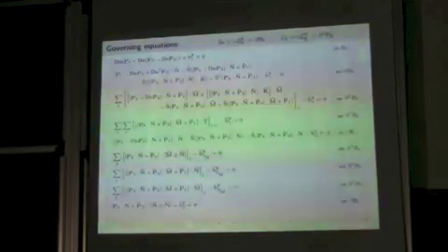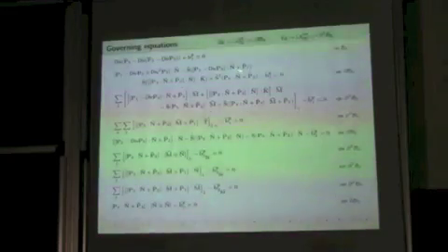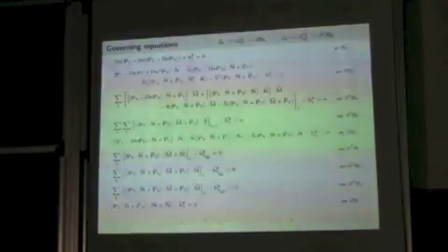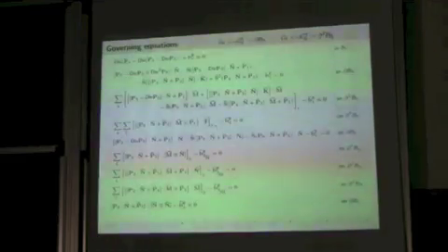It's difficult to see what's going on in detail, but for instance, it's interesting to see that your P hat 1, which is your surface stress, is adding to P2, which is the second gradient bulk stress, and to the divergence of P3, which is the third gradient bulk stress. So if you look at this structure, it tells you a lot, and we have also defined these S hat operators, which are like a surface divergence of a projection of a surface quantity, to simplify the equations.